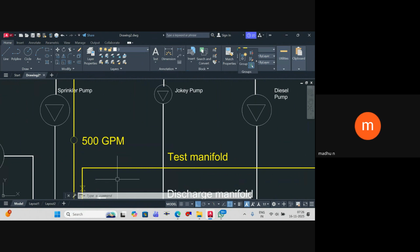Of course, nothing major will happen, but the first thing that can happen is your pump discharge pressure will continuously increase, which results in an increase in your current consumption. So you'll have a breaker inside your system because of overloading, and the starter panel will automatically switch off. Clear? What if it is not off? If it is not off, then your motor will burn.